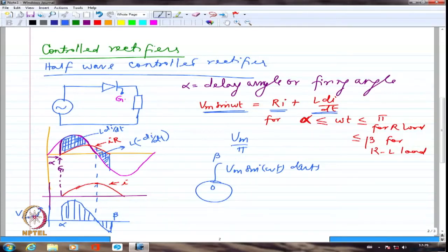But we are looking at the overall voltage across this. We are not segregating IR and L di by dt. We are putting it together. So these two are exactly in parallel. So whatever is the voltage here will appear here. Got it? That's the reason.